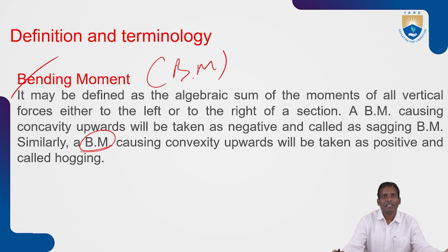So it may be defined as the algebraic sum of the moments of all vertical forces either to the left or right of the section. In the previous case, we were considering only loads, but here the moments. You are taking moments about A, on the left side or the right side. The sum of the moments of all vertical forces either to the left or right of the section.